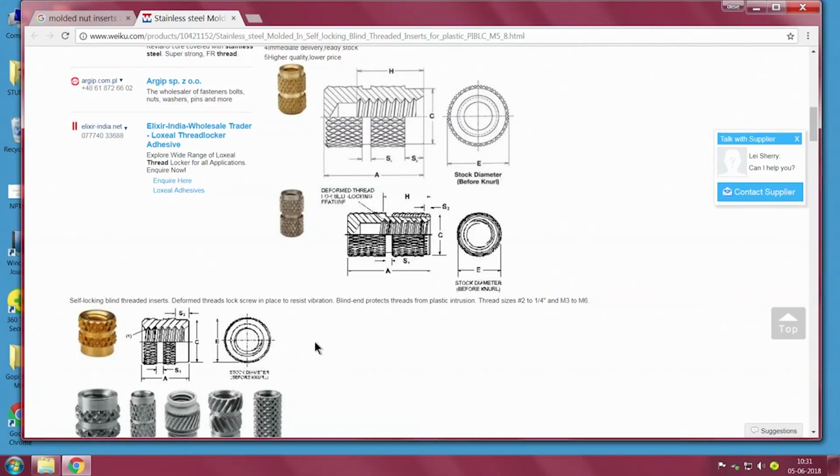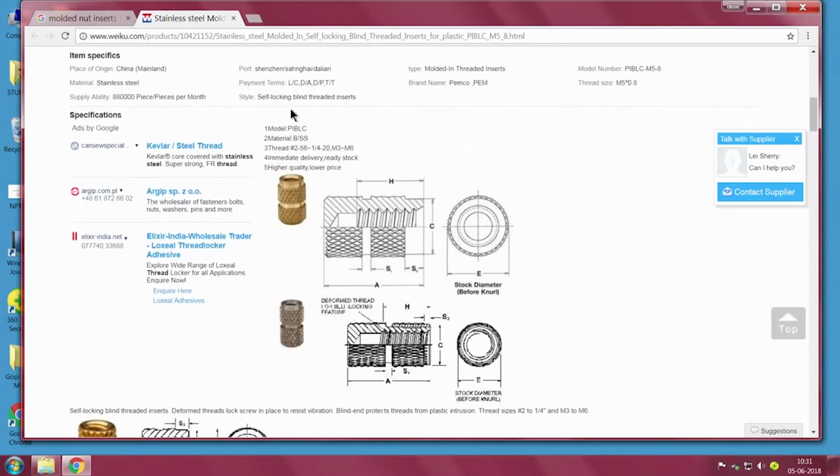Can we use it in our rapid prototyping? No, because we still have an issue as we build layers. In case we put this insert there, it will get into the way of the nozzle, and if you try to push the insert after it is made, chances are it will not go well. So, it does not sit well because the material is not a free flowing material like fully molded plastic, especially glass filled nylon or aluminum. So, we have to look into some workarounds.